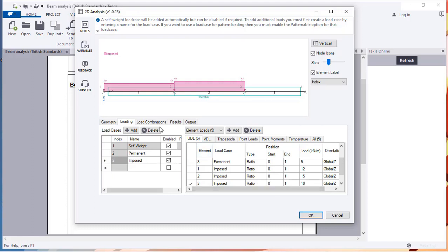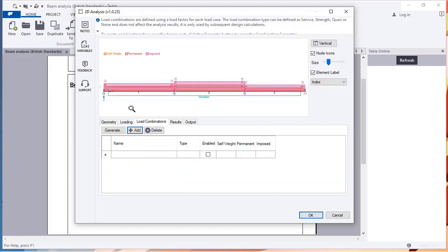So then I go to the load combinations. The load combinations are not important in the analysis, but they are more important normally in design. If I want, I can add them on my own. I can just click dead plus imposed. These are the ones that I want. For the self weight, normally this will be 1.6 if I'm not wrong, then 1.4, then 1.6 again.